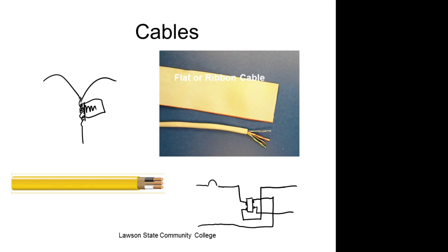So when we say it's not legal to loop it, it means I can't come in here and strip it and loop it around and send it out like that. You can't do that. So you've got to break it, right? Does that make sense? So all your parallel is done out in the house. Your parallel is not done at your panel box. It's done out in the house from plug to plug to plug to plug to plug, right?